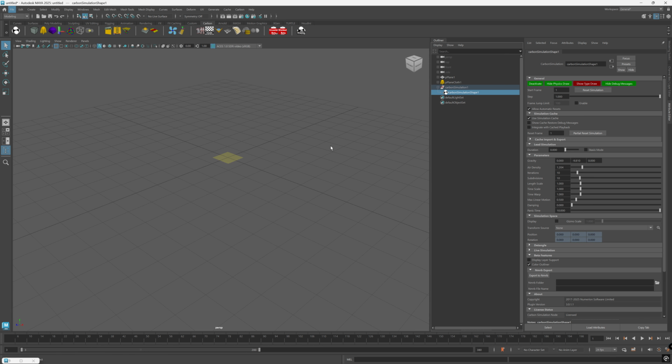Next up, gravity. Per default, the gravity is set in the Y direction to minus 9.81, and this is meters per second squared, which is the gravity we find on our planet Earth. Obviously, if I simulate this now, you get results that you would expect. And if I reduce the gravity to, let's say, -1 only, then what we get is gravity that's much lower, which you would find on some other planet in our solar system, for example. And if you set gravity to something positive, like 1, well, no surprise here, it's going to go up.